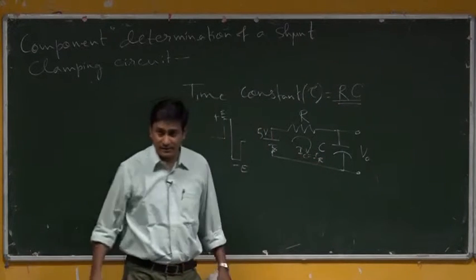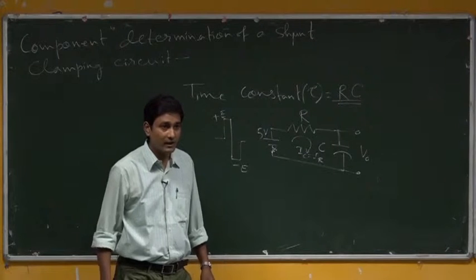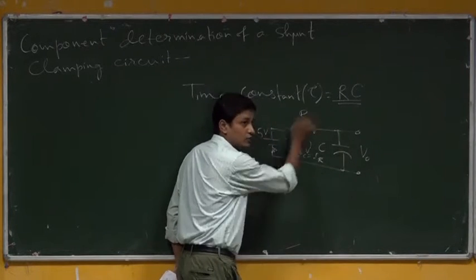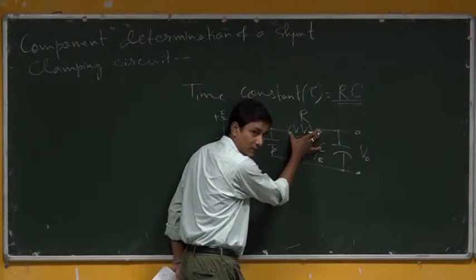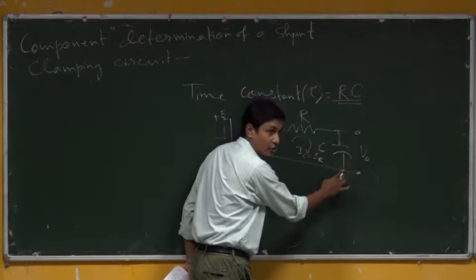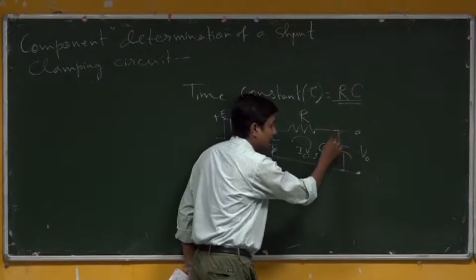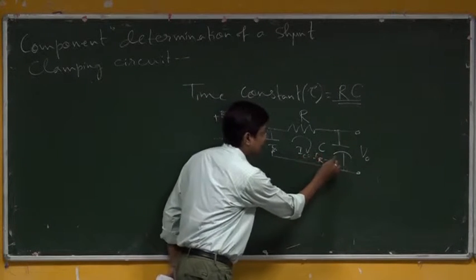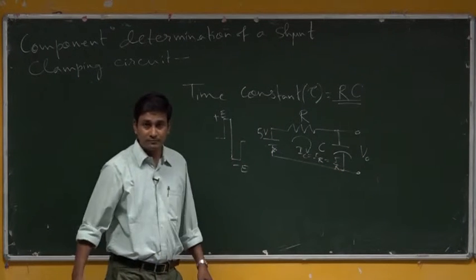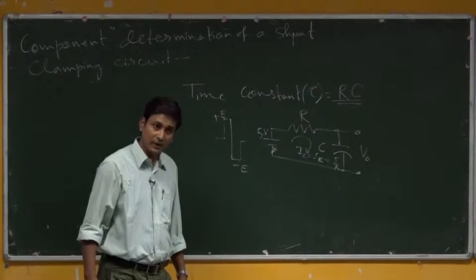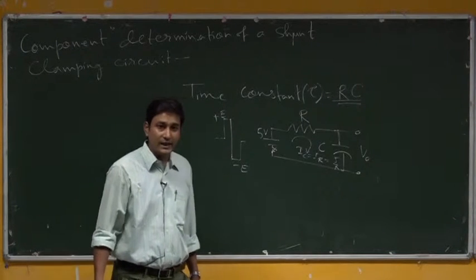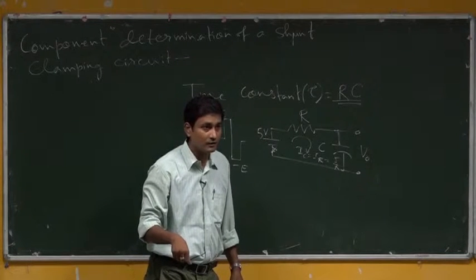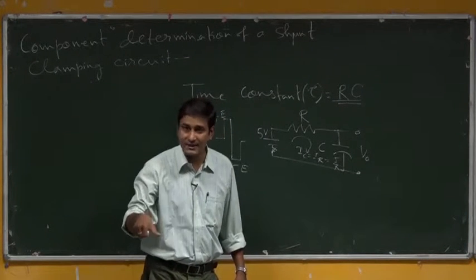In that case, you will say yes, current flows. Why? You have applied 5 volt here, and through this path you see some potential drop supposed to come here and here, which is 0 now. If the potential is 0, it is effectively a short circuit. So, the current which you will see here is nothing but 5 by R. But you are saying that the potential across the capacitor is 0, but still current is flowing. Maybe some confusion arises there.